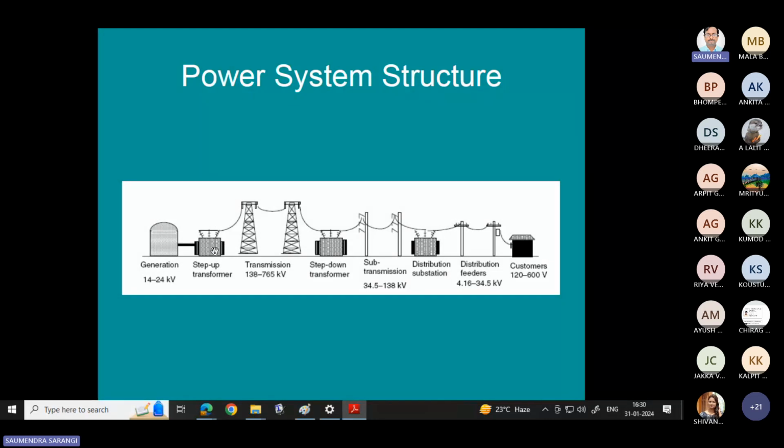In this slide, we may see where the differential and other protection schemes will be utilized. Basically, in the distribution system, our protection will be either overcurrent protection or differential protection. In the case of transmission lines, we protect the system using distance protection, and many other schemes are utilized here, like PLCC, power line carrier communication, and carrier-aided protection schemes. We'll see all these protection schemes here. And in the case of generation and transmission, we'll be going for unit protection schemes.